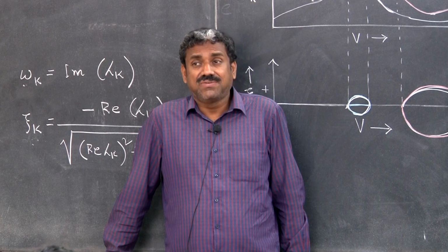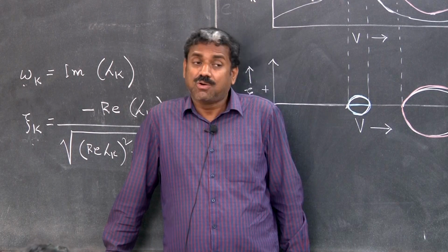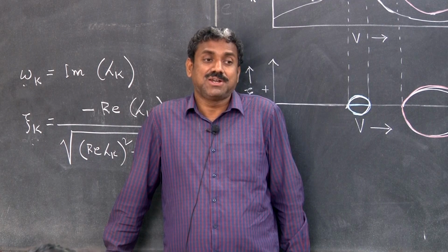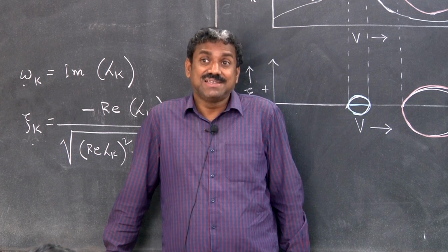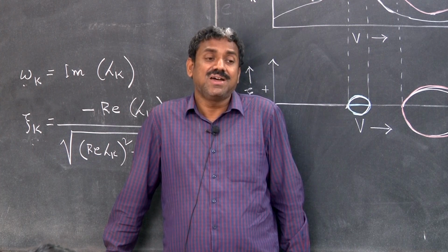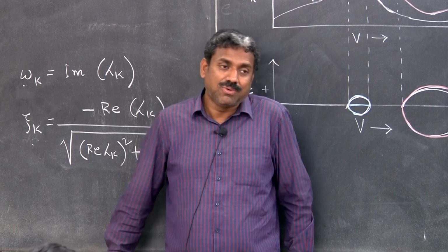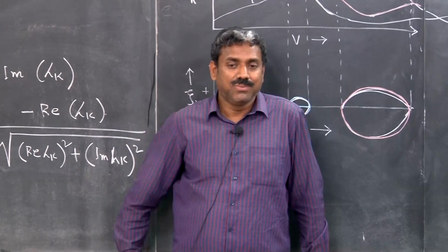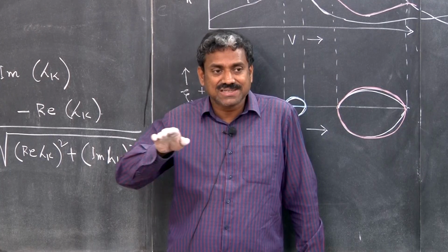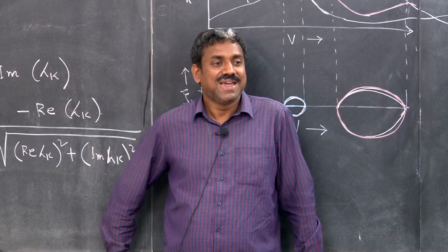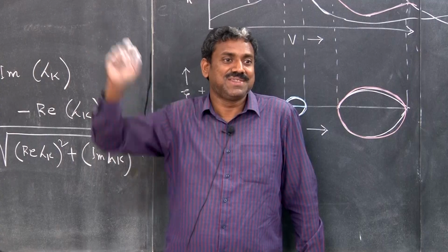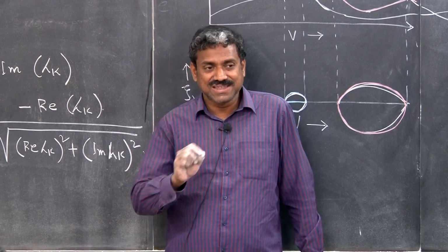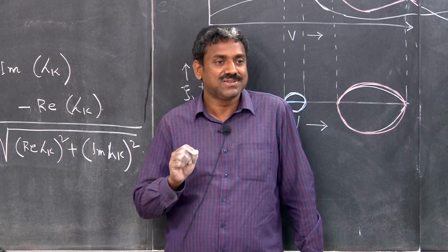Other kinds of aerodynamic instability also happen in chimneys, and chimneys also need to be tested for aerodynamic instability. So, once again you do the aeroelastic modeling for the chimney and put it in the wind tunnel, and then you slowly increase the wind speed, and then you will see suddenly there is a huge jump in the vibration, okay, and that critical velocity is taken as the velocity which is triggering flutter.